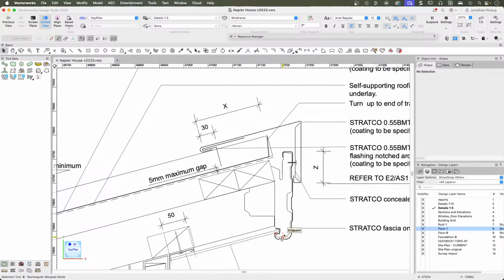Now, this is what this little upstand here is for. When the water tries to come around and climb uphill, it can't. So it gets to the end, there's a water droplet on the end, it can't travel through into the building, it drips off the edge. It's known as a drip edge. If you look at old stone buildings, every old stone building had a ridge underneath the sill, and that sill was the drip edge. That ridge stopped the water from being able to progress into the building.